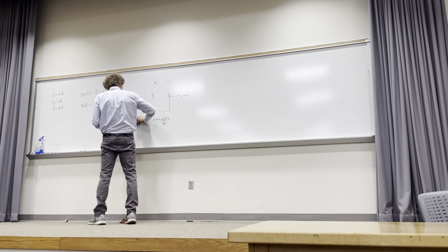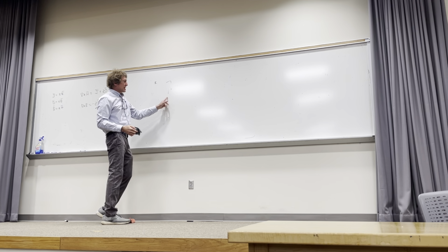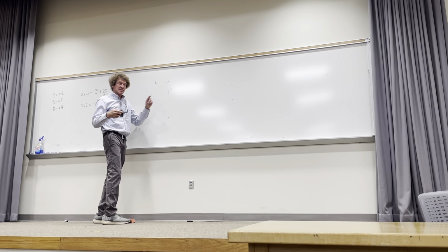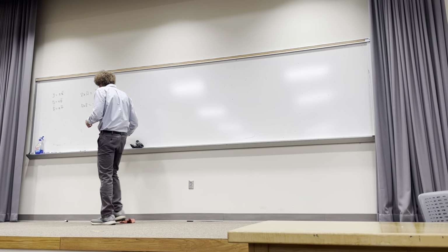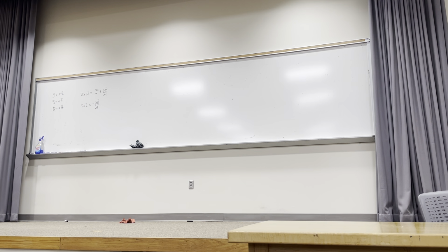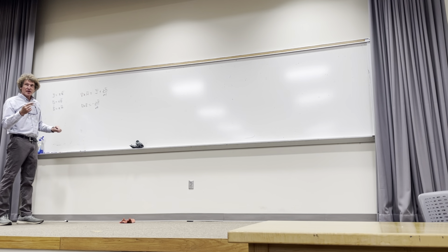So now, I did show you, remember I had L, I replaced L by j omega L, right? Because it was the impedance. So now, the real truth is anytime you have a time derivative, if you're going to do something in a phasor domain, a time derivative just brings out a j omega. Do y'all follow me on that? So, now I'm going to go ahead and show you Maxwell's equations in the phasor domain.